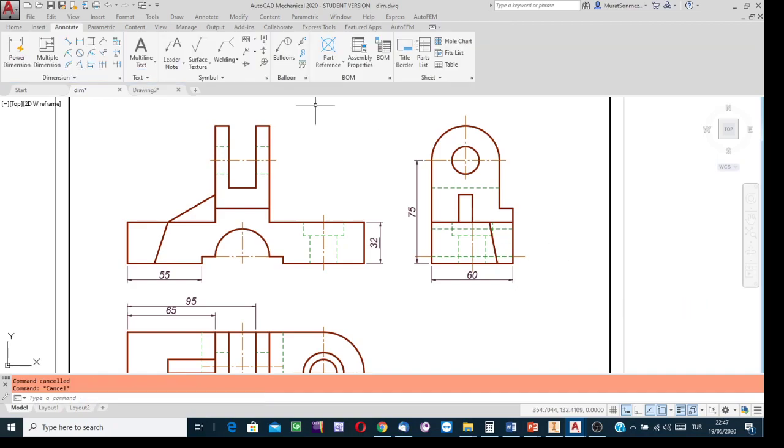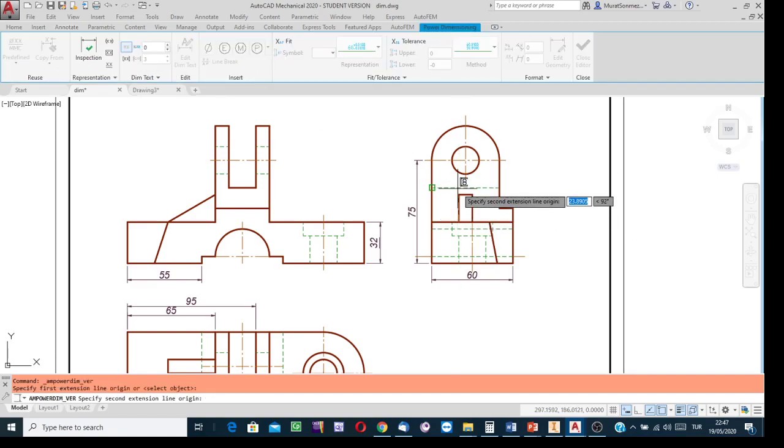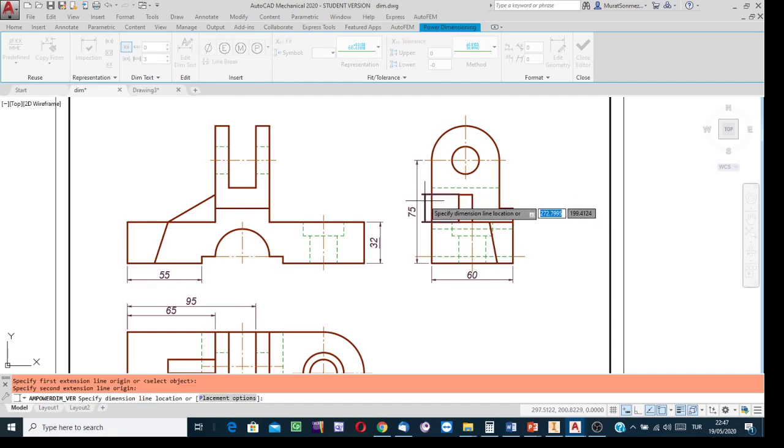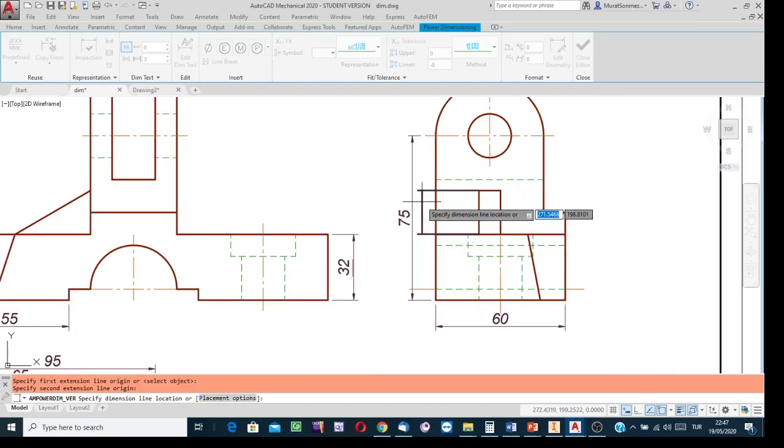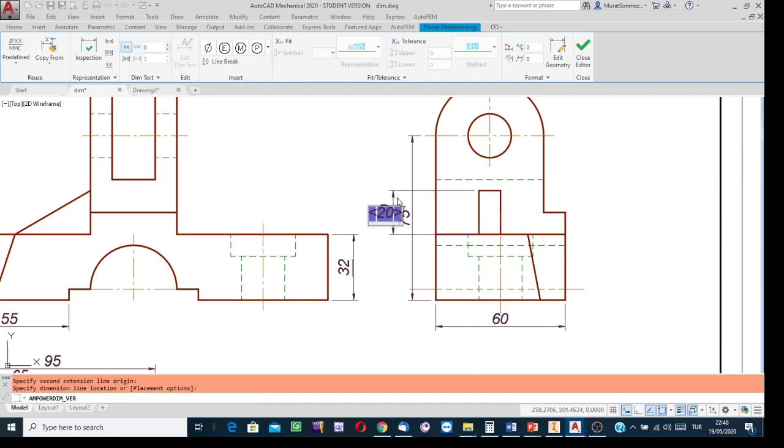Press escape button, and then, well, since I forgot this smaller distance first and then the larger distance, if I indicate this distance over here, then the space between the dimension line and the boundary of the projection won't be 10 millimeters. If I indicate it over there, then it is going to be a violation, because the rule says to avoid having intersections along dimension lines. This is really a poor practice. Show the shorter distances first and larger distances later.